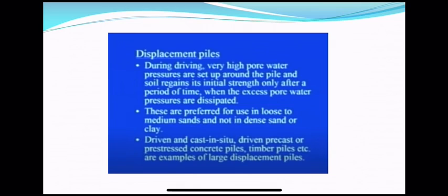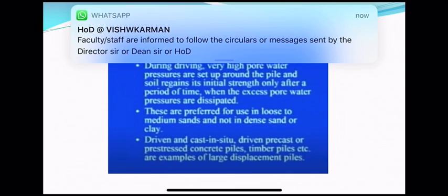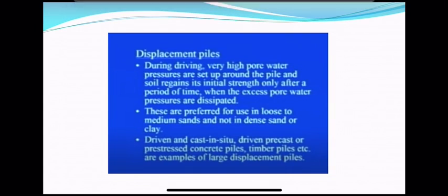That is why it is not preferable in case of dense sand. Now the various types of large displacement piles are driven cast in situ, driven precast or pre-stressed concrete piles, timber piles, etc. These are various examples. Now what do we mean by the term driven? Driven means you are driving the pile. Simply the pile is constructed, and you are driving it with some mechanical hammering or some vibration technique, so the term is known as driven.